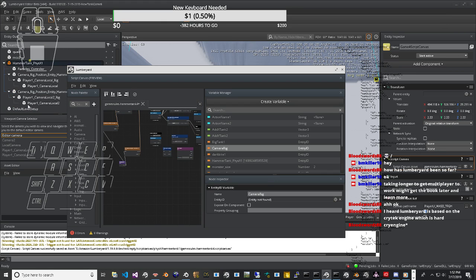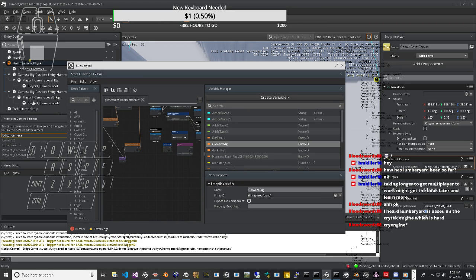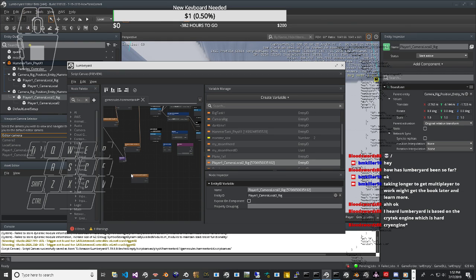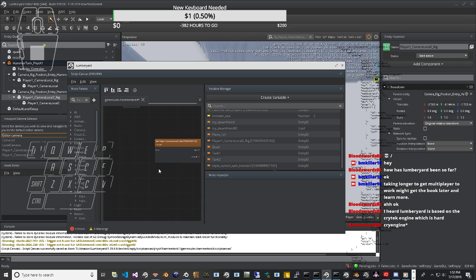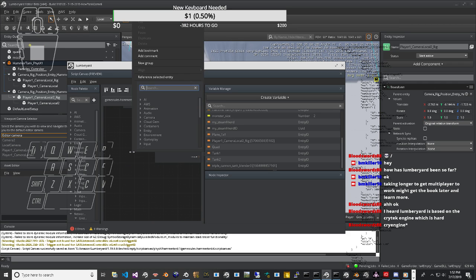Precisely, consider the line formed by the intersection of Earth's xy plane with car's xz plane. The angle of that line with respect to Earth's x-axis is the instantaneous heading of the car. It becomes undefined only when the car points directly up, standing on its tail, or directly down, standing on its nose. To emphasize, heading is measured in the Earth frame.